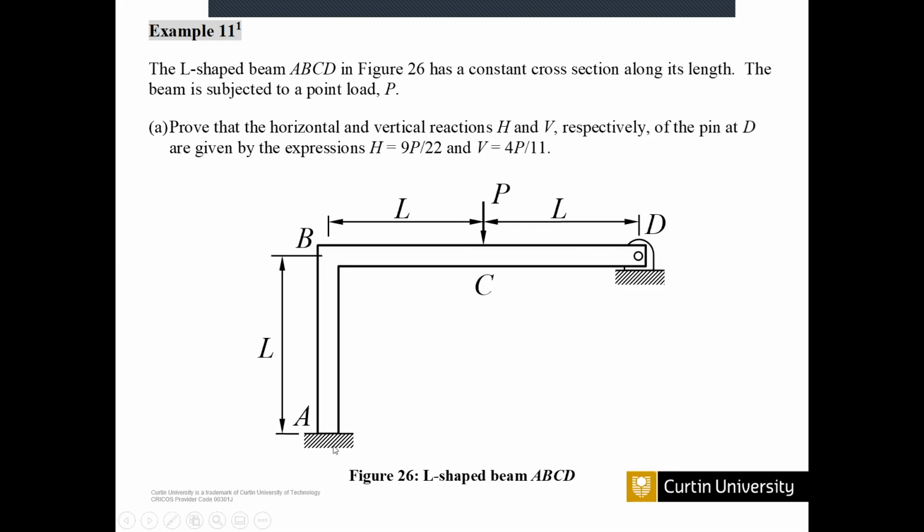In here, bending moments are also available along with the horizontal and vertical force, because this is a fixed end. This one doesn't have freedom to rotate, so there is a bending moment. But it doesn't have freedom to move in this direction or this direction. That's why there are reactions available vertically and horizontally.